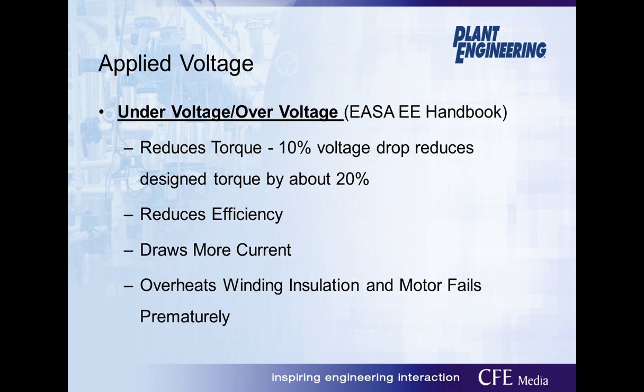All I can say, and keep in mind we're based in Raleigh, there was enough smoke that day to cook a pork butt, and the motor showed core losses well beyond allowable levels for a rewind after failure finally occurred. So a big no-no.